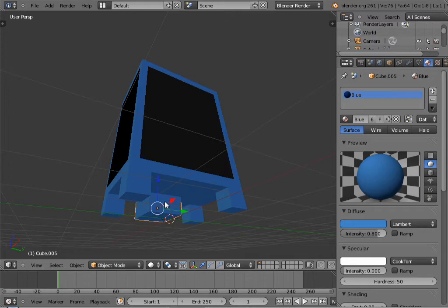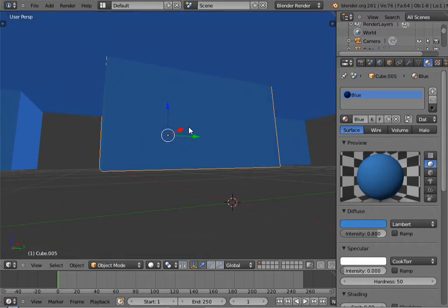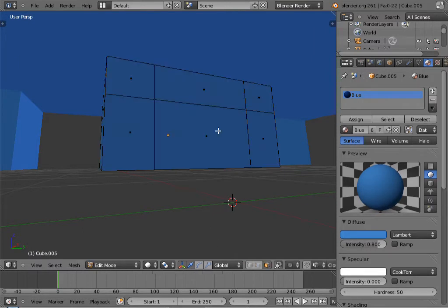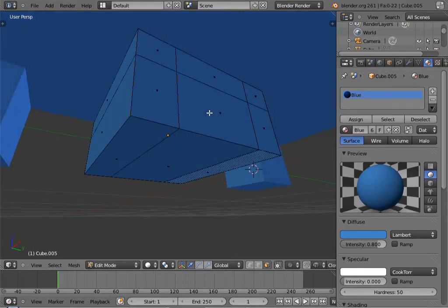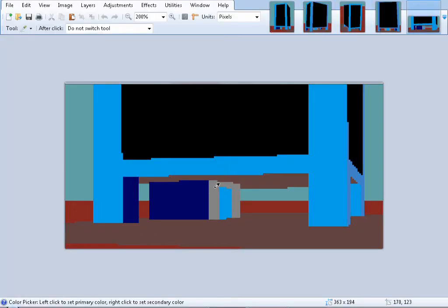So I'm going to right click on the elevator bit, zoom in, and go into object edit mode with tab, and let's see what colours we want. Let's go down here. Now you can see this has got different colours on each side, and it's actually got a different colour for the bottom here, but you're not going to see that. If you want to, you can go in and colour every polygon a different colour, but I'm not going to do that. So I'm just going to select this grey colour here, which is hex 848484, which is right down the middle of grey, absolute medium grey.